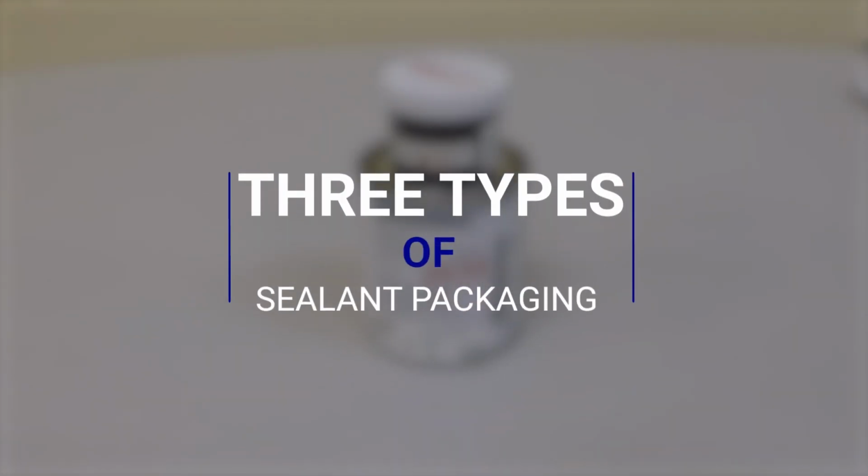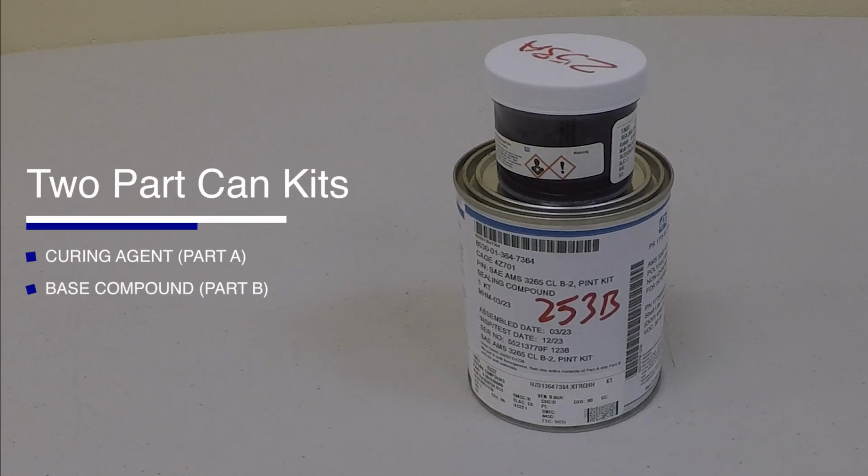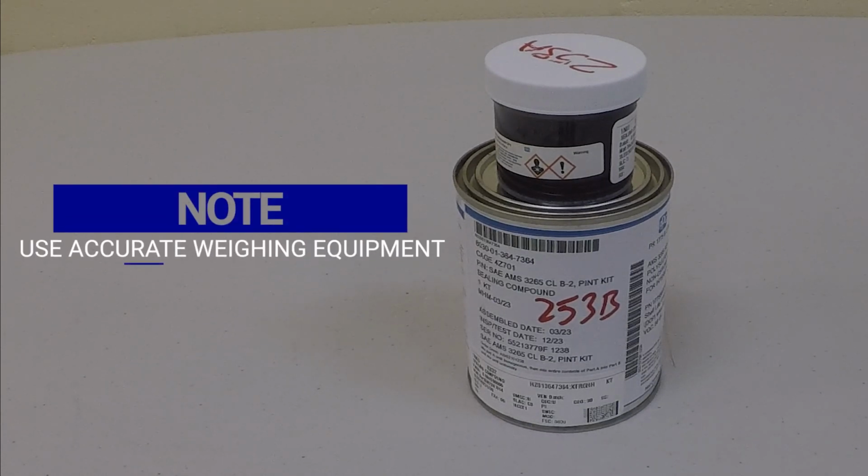Sealants are generally packaged and available as 3 different units of issue. First, the 2-part can kit, a kit consisting of a curing agent, part A, and a base compound, part B, that are pre-measured into separate containers. Accurate weighing equipment shall be used to achieve the correct mix ratio for smaller mixes.